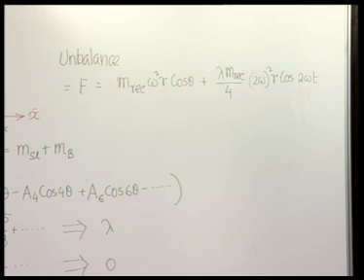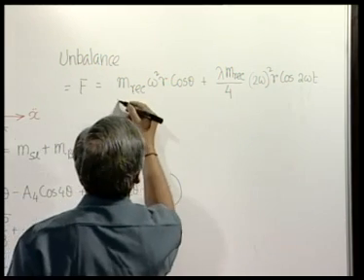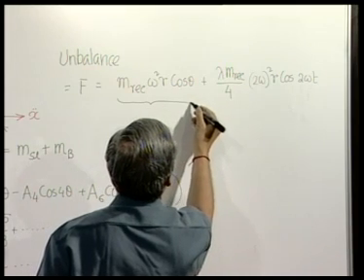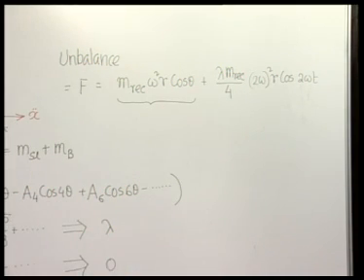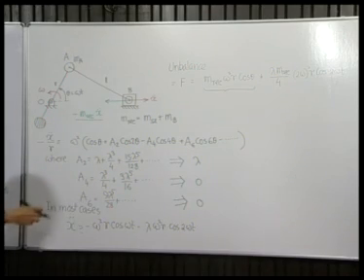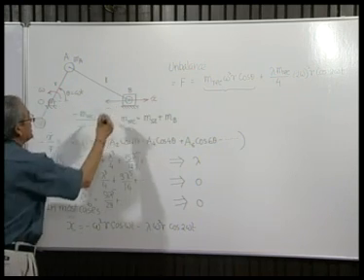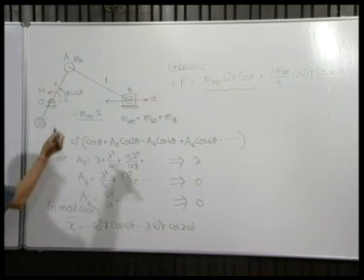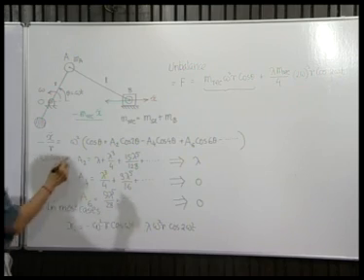So, you can see this is nothing but a harmonic force whose magnitude is equivalent to a centrifugal force, where the reciprocating mass is placed at the crank pin and the crank rotates at its own speed omega. Then its component along the cylinder center line, that is x direction, is that primary component which we call the primary.